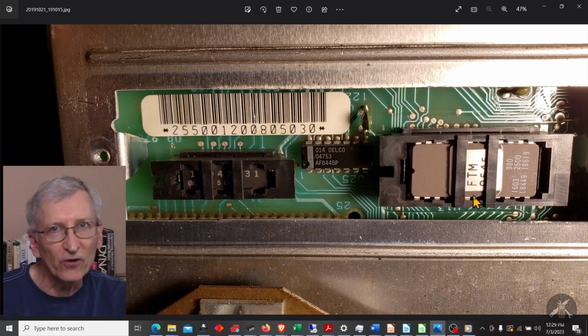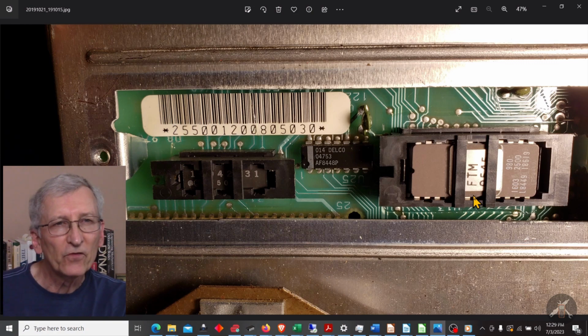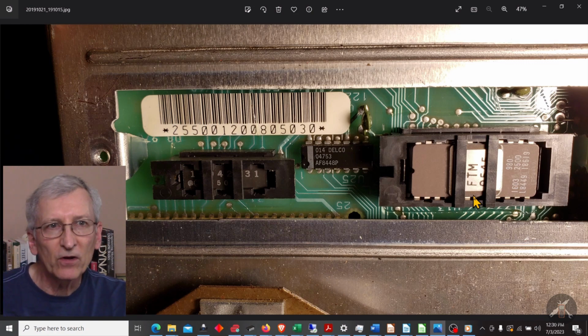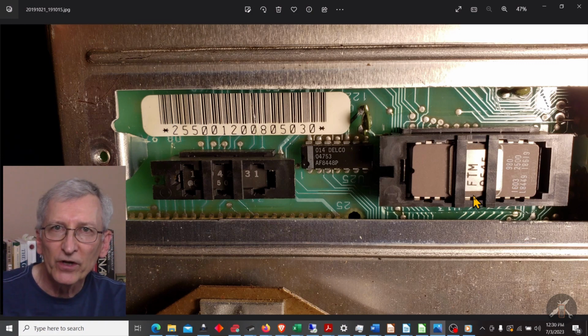If you've been working on General Motors cars, there are famous RPOs for engines like LT1s, right? That's a regular production option. In some cases, there'll also be a broadcast code with that in the plant. A broadcast code tells the plant what to build. And so there will be multiple ECMs that, at the time, Delco would have built, and they'll have a different calibration chip in them.